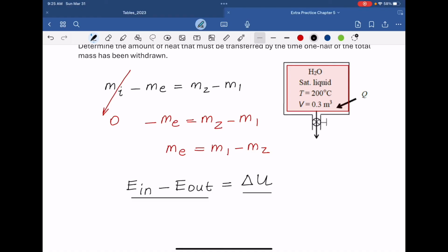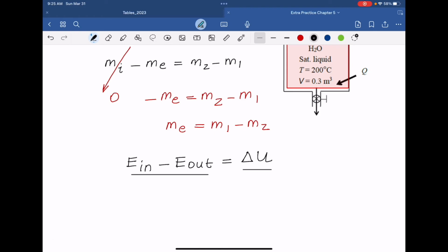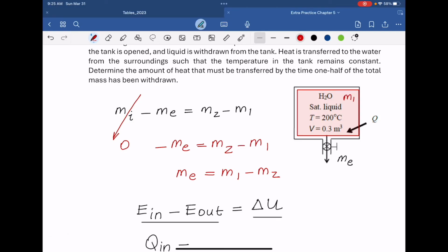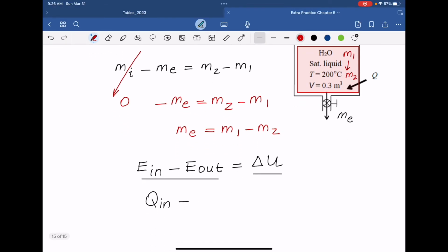So as we talked about it, energies are getting in with heat and getting out with mass. And mass getting out is exiting mass. Inside though we have M1 changing into M2 due to mass interaction. 1 and 2 subscripts here define our state, and E defines our exit mass. Now mass is exiting as ME with an enthalpy HE. Okay, because exiting mass also has its own energy, and we define the energy of the flowing fluid, meaning the mass that is getting out with its enthalpy here.